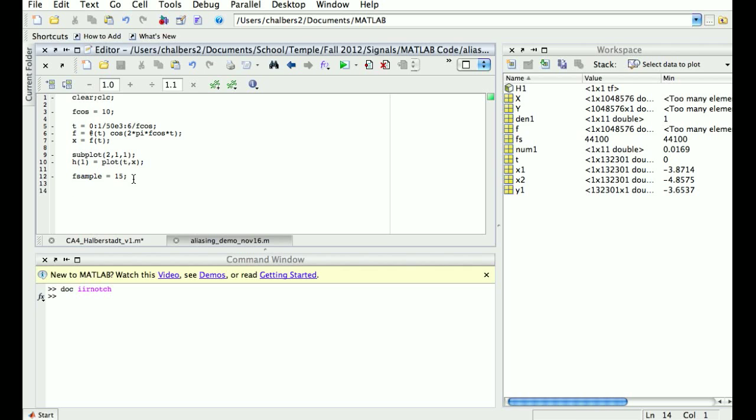The red one is if we were to take the sampled points and reconstruct a cosine, that's what it would look like. So ignore the red for now, just look at the points. Because we're sampling at 15 hertz, this is technically undersampled. If you tried to fit a curve to the yellow points, that's why you're getting the red signal, which looks totally shifted.